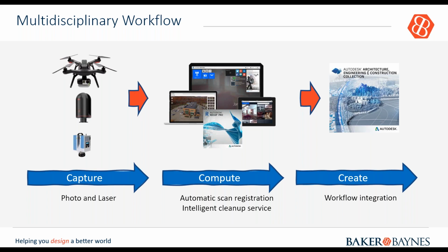And then, of course, if you want to actually recapture the as-built information, you can do a scan again and then import it over your existing model, and you can actually pick up the discrepancy. So it makes the modeling aspect much quicker in terms of as-built generation once you have your Revit model. And yeah, that's just the 3 phases that you will work through in a conventional project workflow.